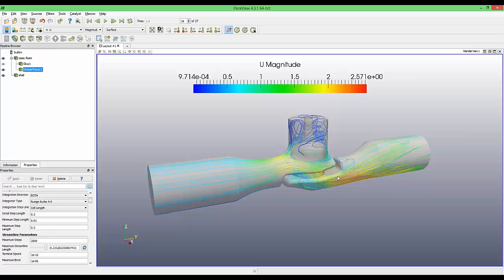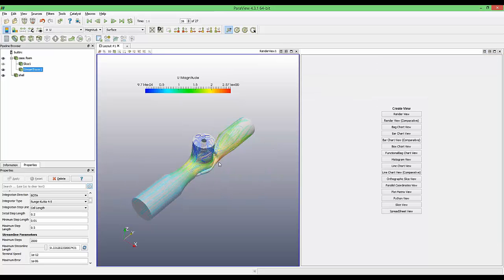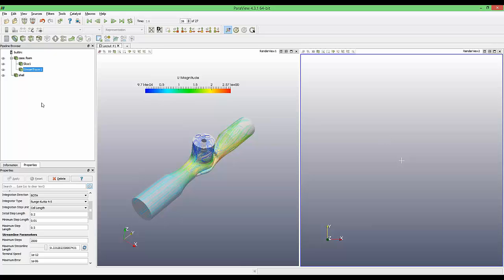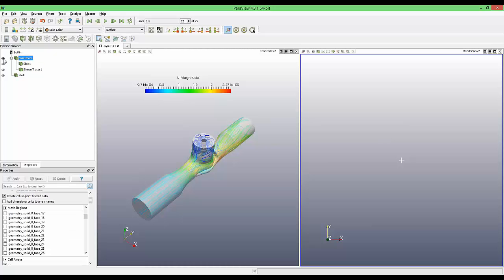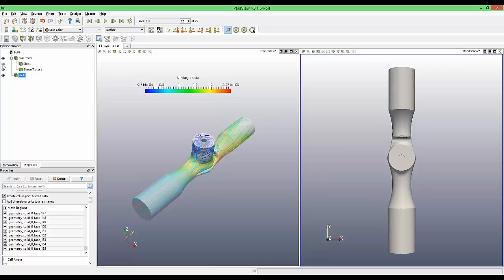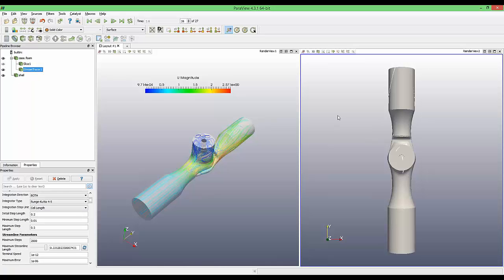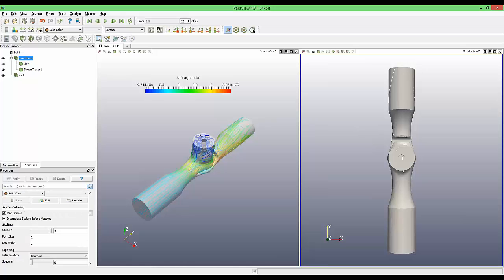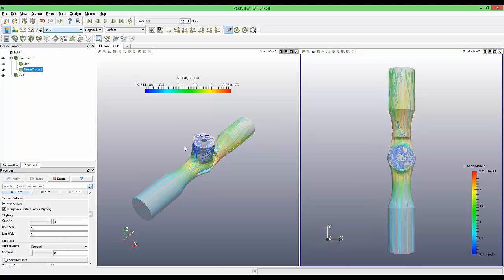visualization of other elements. The next thing that can be of interest is choosing the second renderer to have multiple images shown at the same time. With the second window open, I can choose the renderer view and decide which data elements should be visible. I'll choose the stream tracers and the streamlines. Further, once more, I will add the opacity factor to the whole body and choose a color for the stream tracer.